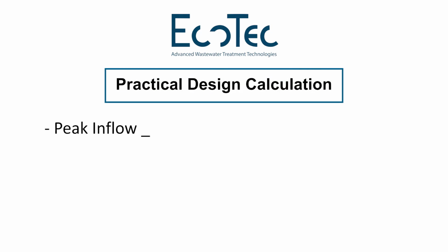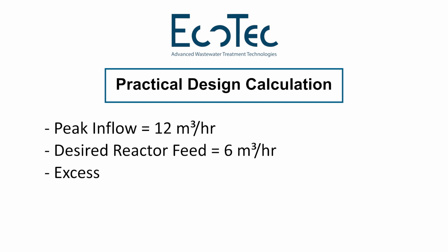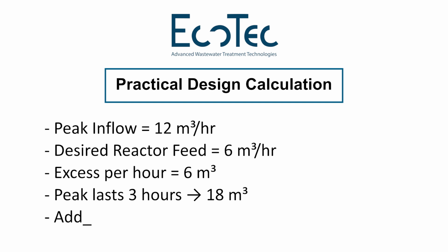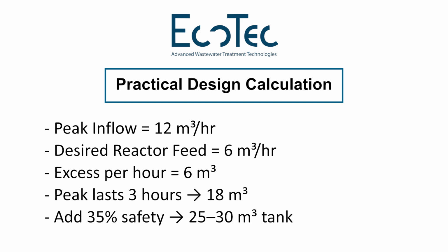What can be the correct approach to design? As you see, we have already identified a revised peak load of 6.5. With this, if we calculate the volume of the equalization tank or the collection tank to be almost 12 to 15 hours a day, this should be the right sizing of a school sewage treatment plant collection tank.